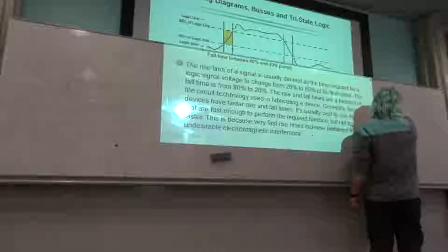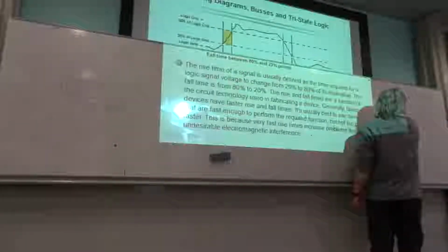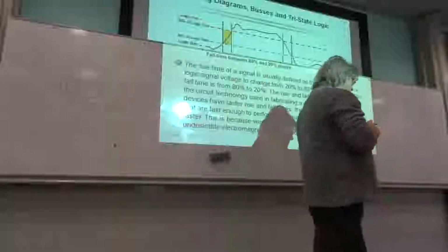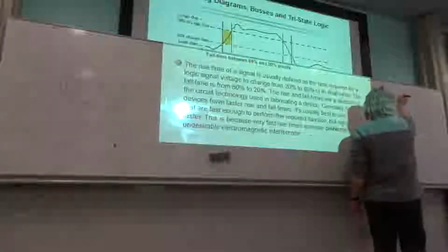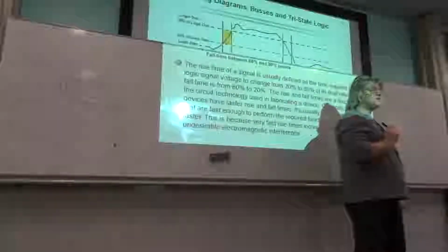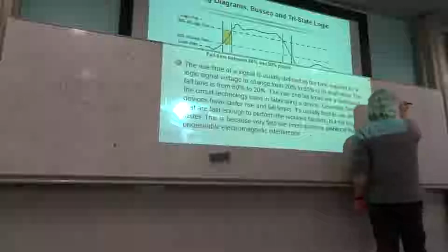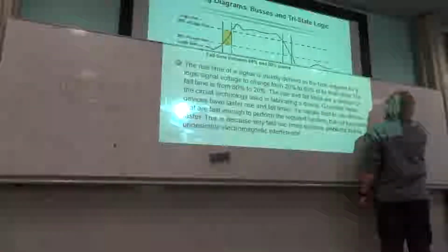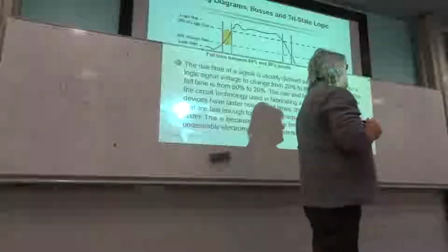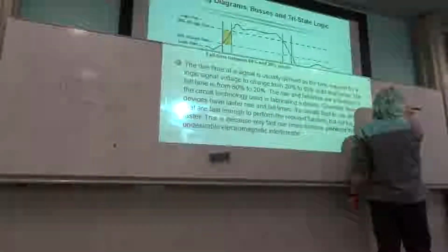For those of you that remember things like the TTL 74 series, I don't know if you've come across those, there are a whole set of families associated with that. L, which is low power, which is quite slow, quite long rise and fall times. There's LS, which is a little bit quicker, using kind of Schmitt triggers and things, I think.